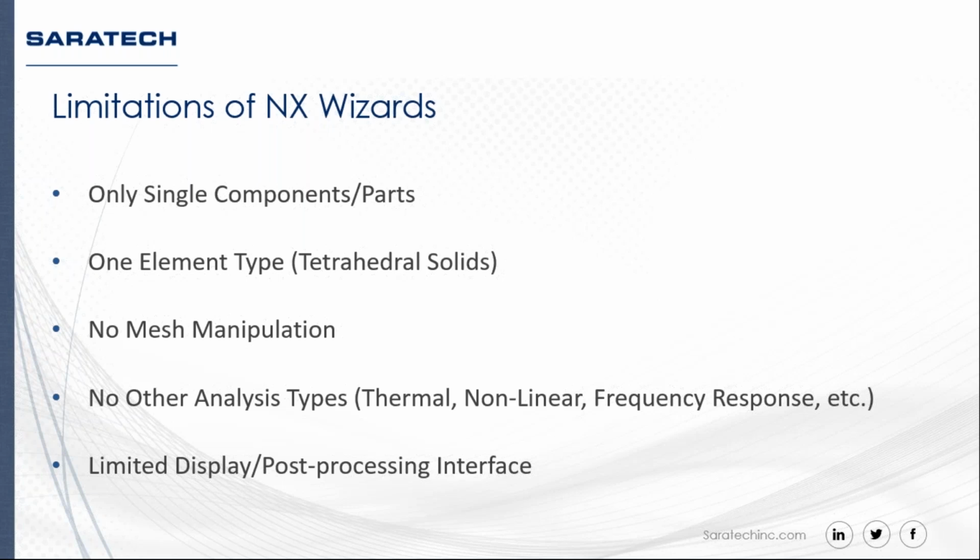Then we have no mesh manipulation, which you'll see in the software. It will ask you for an element size, and once you input that element size, that is what you get. There's no finer tuning of the mesh. There are also no other analysis types than the ones that I've mentioned. So we only have linear statics, modal, and fatigue. There aren't thermal or nonlinear or some other analysis types.